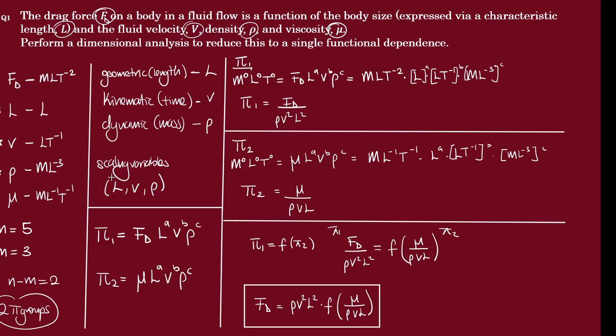And from that, pick your scaling variables for length, time, and mass, which are going to be your independent dimensions m. You need to have the same number. You can do this beforehand to get an idea of what the pi term is going to look like. And solve for pi 1, solve for pi 2, solve for the necessary pi's. And at the end of the day, you will have your expression.